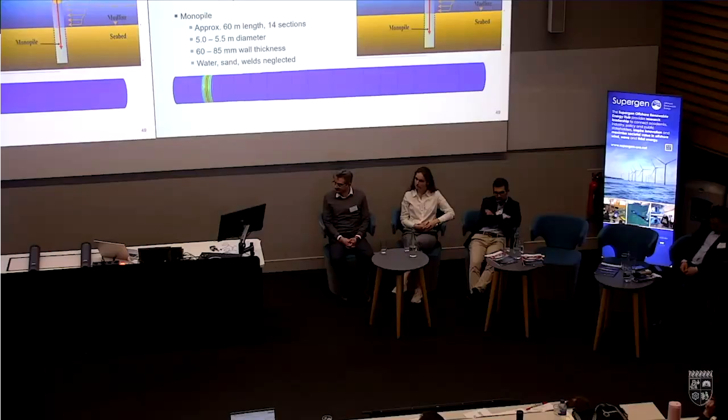So the idea we are looking at is, if we put some sensors close to the transition piece, can we send a low frequency ultrasonic wave down that monopile and gain information about defects, fatigue, and corrosion developing in that structure? Here is a finite element simulation of how that could work, using the actual dimensions of a monopile currently somewhere in the North Sea.